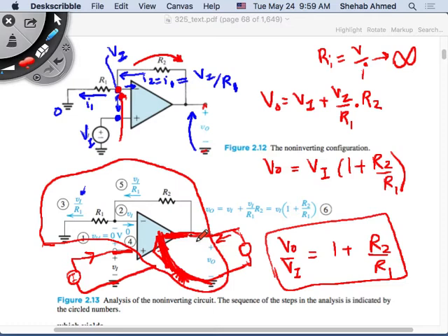After a certain amount of current, I don't know how the ohm meter measures a short circuit. An ohm meter is basically an ideal voltage source. It supplies an ideal voltage that is known, and depending on the current that goes out, it takes this known voltage divided by the current, and you calculate the resistance. But in this case, the current should be theoretically infinite because I don't have any impedance or resistance. Practically, an ohm meter cannot provide infinite current.